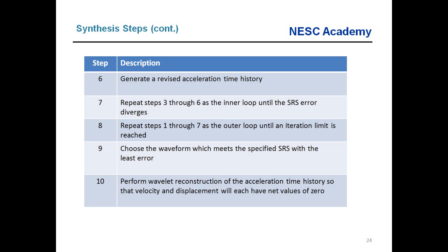Well, for shock, I just decided to be a little bit clever, probably more clever than I should have been. And we're going to do something that's going to turn this into a bit of a Rube Goldberg process. But I thought to myself, we could take that damped sinusoid series and model it as a series of wavelets. And if we model it as a series of wavelets, then the net velocities, net displacements, and net acceleration values will all be zero. It'll be a very good stable waveform.